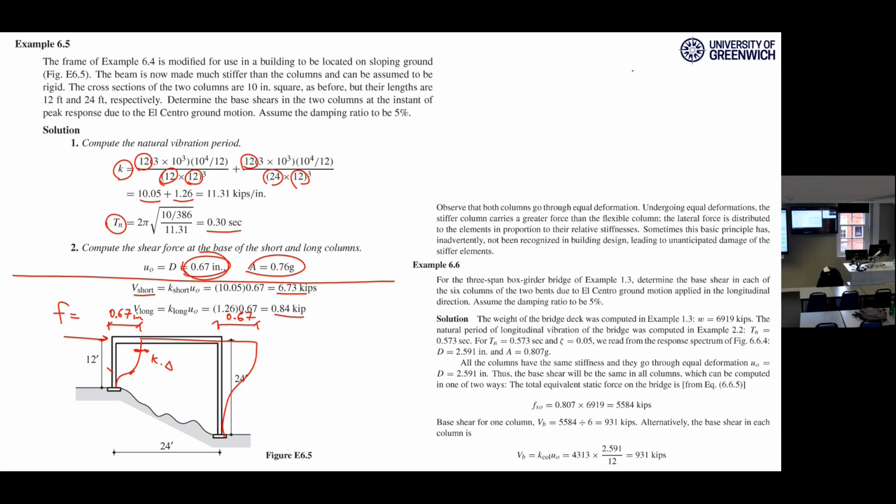We discussed it in the structural design. The shear design in the Eurocode is somehow totally different from the American, with two different perspectives. If you design shear reinforcement with the Eurocode, you will come up with quite a lot of reinforcement rather than American. Apart from this one, the other things are more clear, probably more advanced. I think so. But for the shear design, Eurocode is probably better. At least more conservative, let's say.